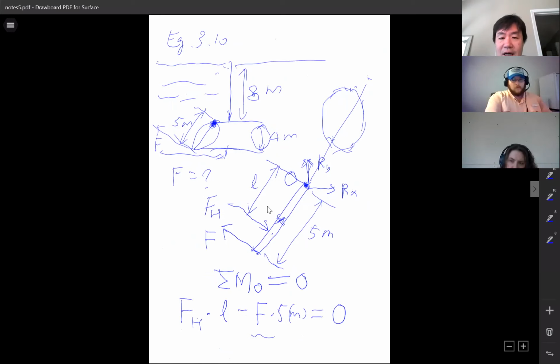Two things here. To calculate the force on a plane surface, okay, I guess for now you should remember how to do that, right? Just the area times the average pressure on the surface. The average pressure will be the pressure at the centroid location, right? We did a quiz last time. I kind of forced you to draw this with a mark on the centroid, like this.